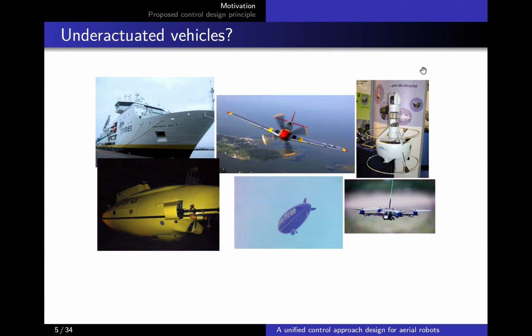Here is a ducted fan, a VTOL vehicle developed by a company in France. The name is Bertin Technologies. It is a vehicle that looks like a quad. The quad, I guess all people know what the quad is. You have 4 control inputs. Here it is a bit the same. You have only one thrust, but there are 4 rudders under the duct that can orient the vehicle.